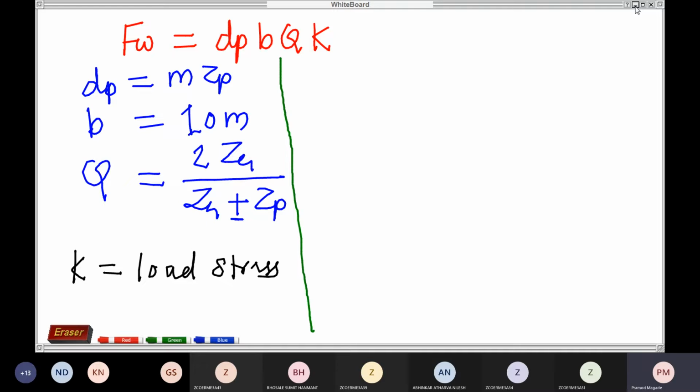Why? Because the load is directly taken by that material. If I'm using a weak material, it will have to take the load and can break very easily. So, as per the rule, load stress factor is, of course, because of the load acting on the surface of the teeth, and it depends directly on the material. So we'll have to assume the material consideration for the load condition. So what are the considerations?